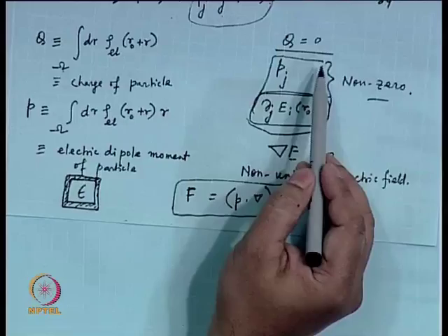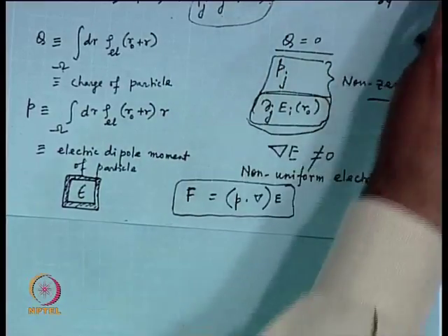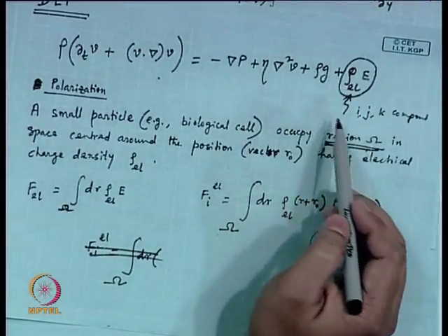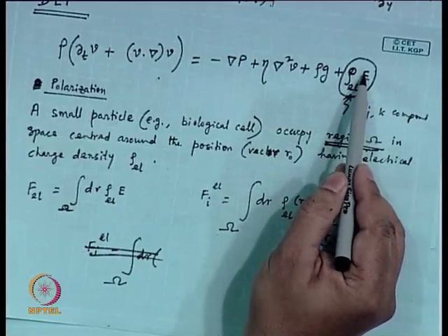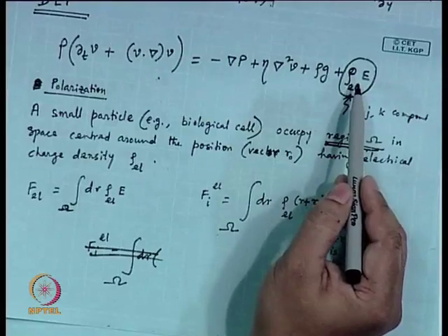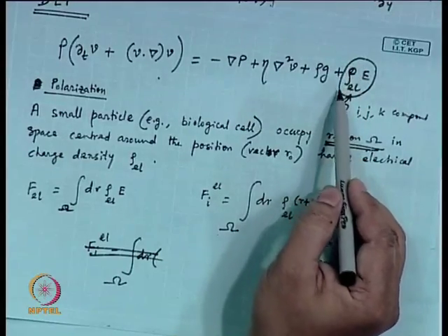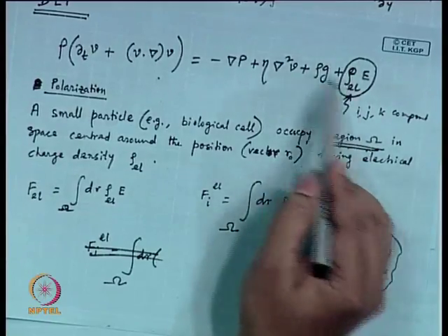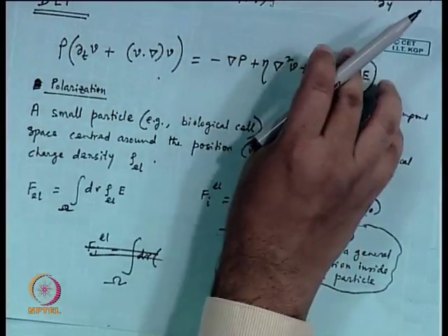And keep this very clear: here the q is 0. In the Navier-Stokes equation, the conventional body force term, we assumed a uniform electric field. When we talked about electroosmosis, we talked about a uniform electric field, and a rho_E present, which gave a body force. Here this component is 0. So, ideally there should not be any body force, but the body force arises because of the P term, not the Q term.